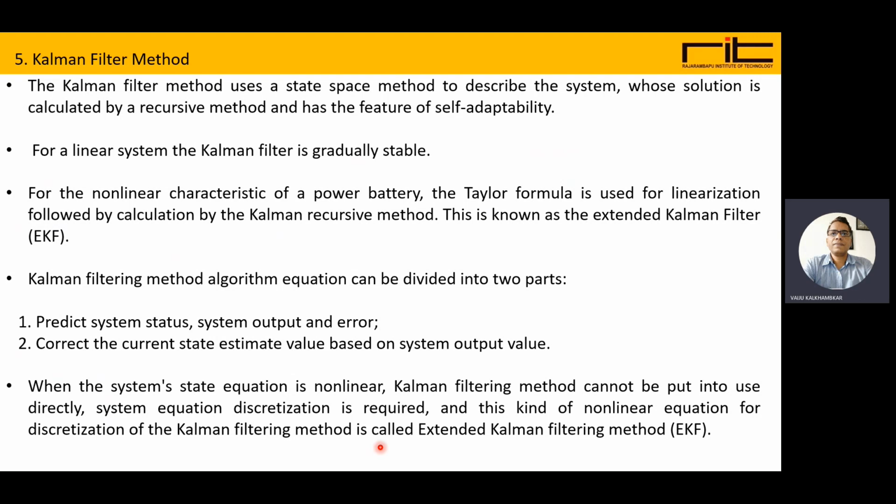For a linear system, the Kalman filter is gradually stable. For the nonlinear characteristics of a power battery, the Taylor formula is used for linearization, followed by calculation by the Kalman recursive method. This is known as the extended Kalman filter method, that is the EKF.